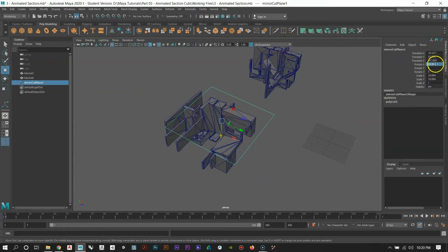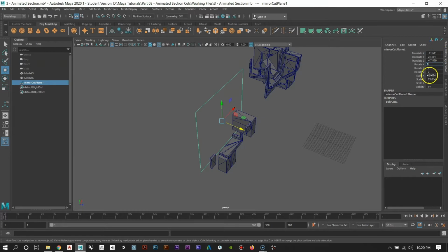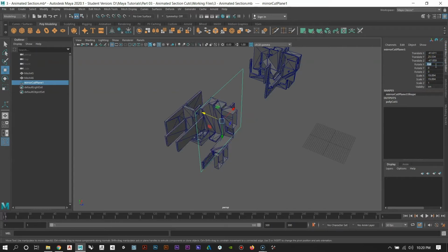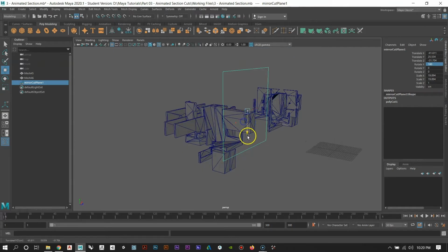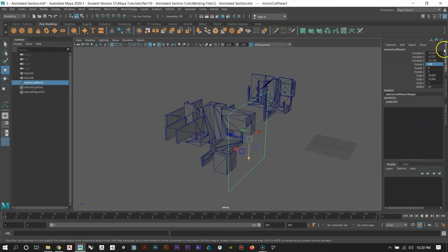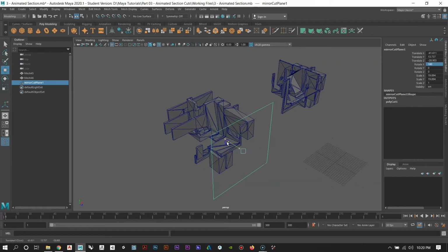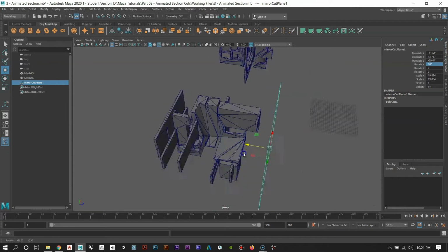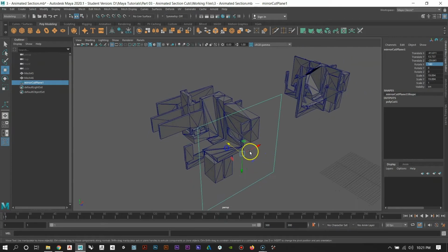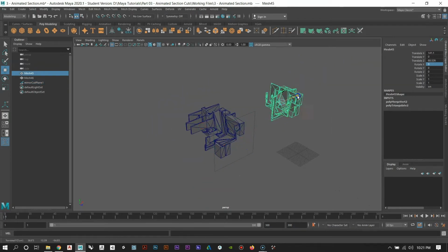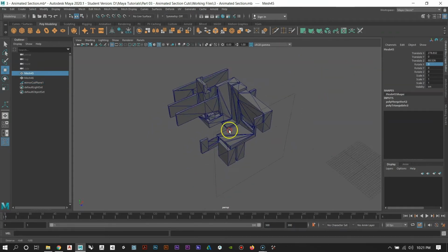So let's set this thing back to our normal rotations. I want this at 180, so it's cutting from this side. Pull it down. Okay, I've got it at this position. I always start it fully outside the model, so nothing's being cut at the beginning of the animation. I'm also going to push it off to the side.